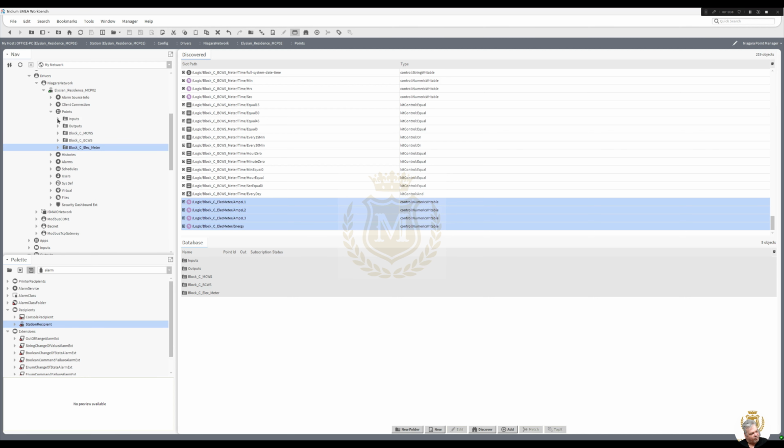But I could have just brought the inputs in and then attached histories. But if we did lose connection to the station, what would that affect? That would affect the LTHW 3-port valve only. The data would still be collected, but we won't be controlling the LTHW 3-port valve if we lost connection.